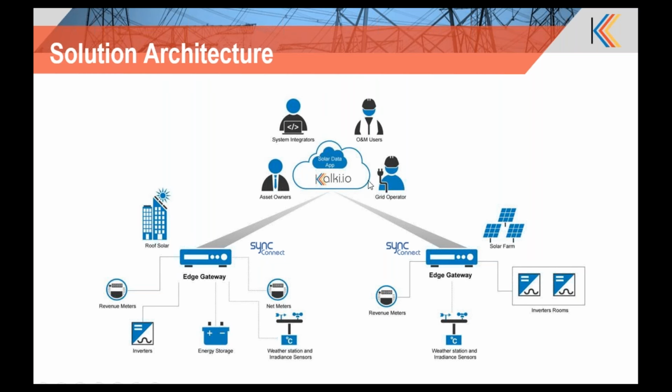But normally, in the case of utility systems, what we have seen is ICCP, Inter-Control Center Protocol, where there's a bilateral agreement between the external entities and the utility SCADA systems on which data can be exposed and exchanged between those systems. That kind of control is provided using the ICCP protocol. That can be used, or DNP3, Modbus, 101, etc. can also be used.